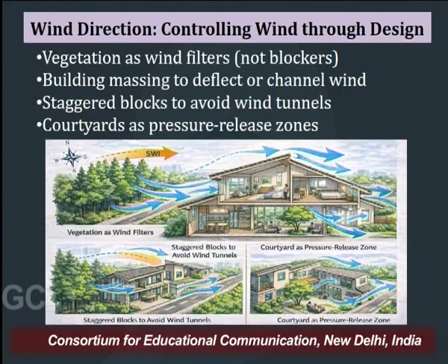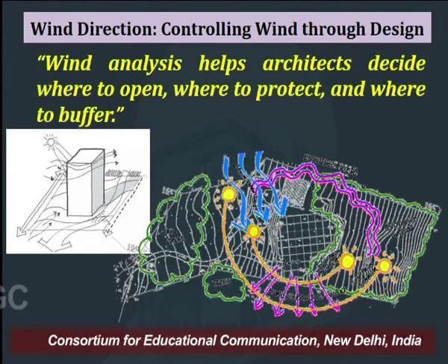The fenestrations on the left side of the section are inviting the wind to travel throughout the house, creating a ventilation effect, so that the overall house is ventilated and fresh wind is circulated throughout the house. So, the wind needs to be controlled. We always allow controlled air to pass through the house and help in the ventilation.